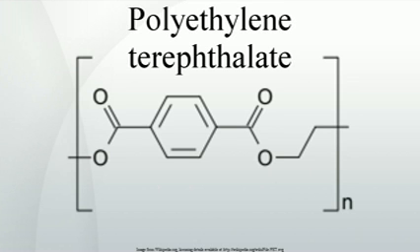Drying. PET is hygroscopic, meaning that it absorbs water from its surroundings. However, when this damp PET is then heated, the water hydrolyzes the PET, decreasing its resilience. Thus, before the resin can be processed in a molding machine, it must be dried.